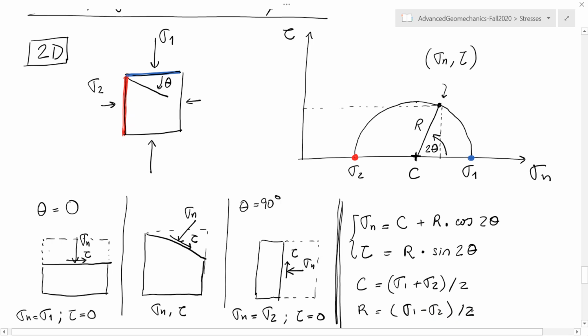All right, so these are all the equations that you need in order to calculate normal stress and shear stress on a plane for 2 dimensions. This becomes quite important, for example, when we are looking at stresses on faults and fractures, because the ratio of shear stress over effective normal stress is what is going to tell you if such a block is moving or not. So let me add a plot over here.